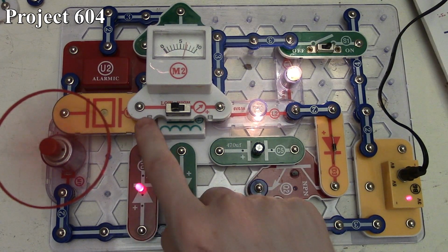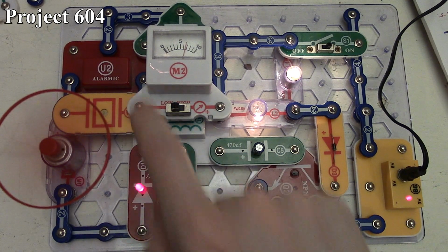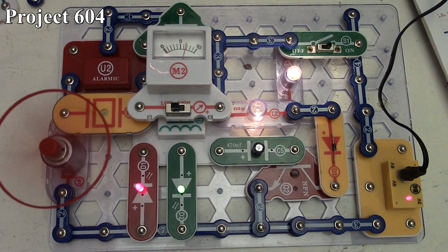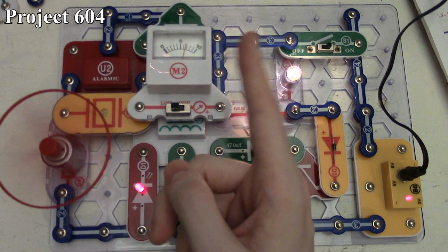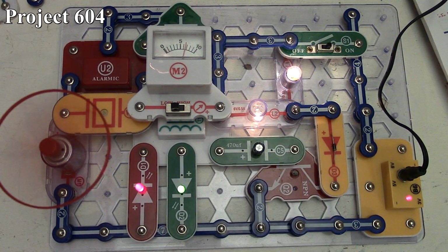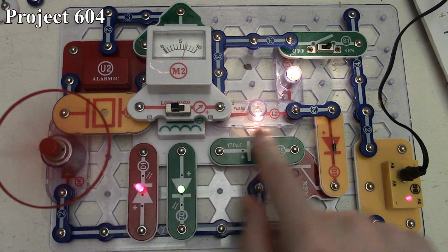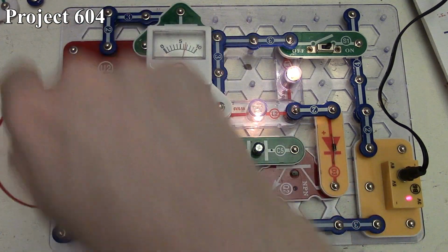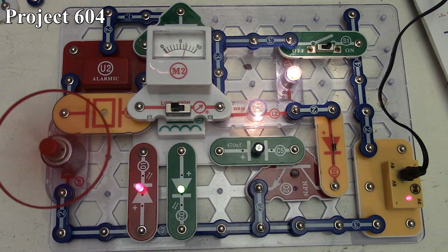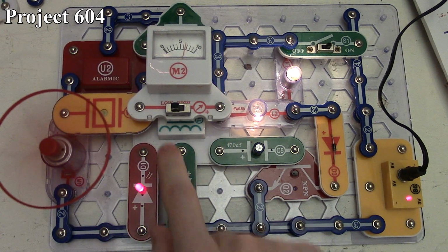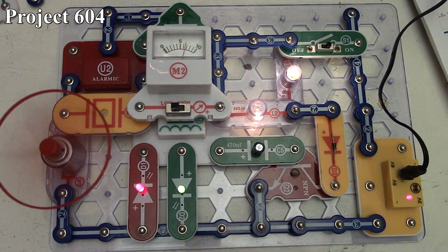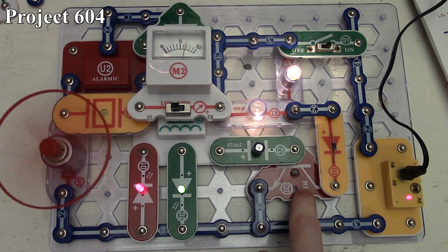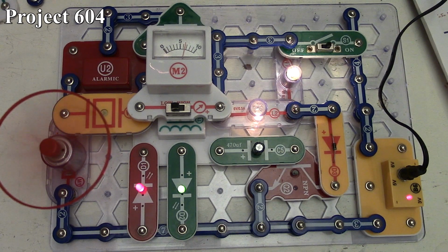So we can hear our output from the alarm IC there as it's again being pulsed by our PNP transistor there. We can see the output from our meter there is hovering a little bit, but it's going back and forth as it pulses. Our motor is running constantly because it's not being affected by the pulsing here, because again it's just pulling the alarm IC's side down there. But we can see some pulsing of our LEDs here. We can certainly see the pulsing of our 3-volt and 6-volt lamps, which again is being controlled by our NPN transistor here from the output of our transformer.